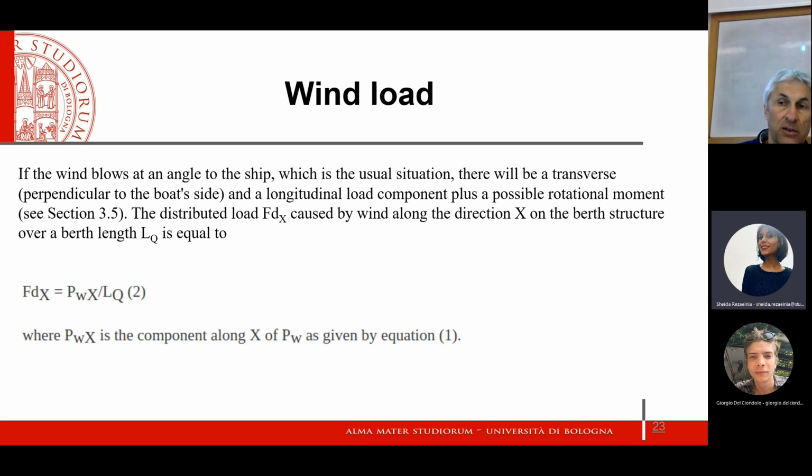And indeed, when we talk about mooring forces, many regulations allow us to distribute the load because we have several mooring points, several springs, and therefore we can simply divide the overall effort by the length of the berth.